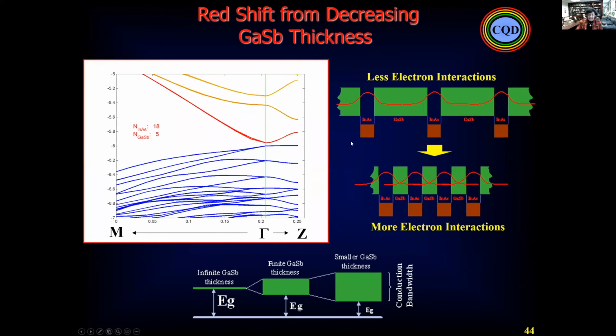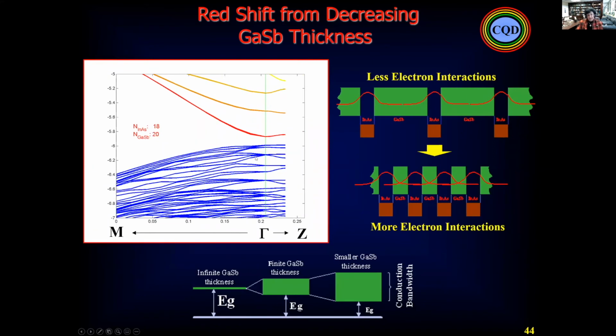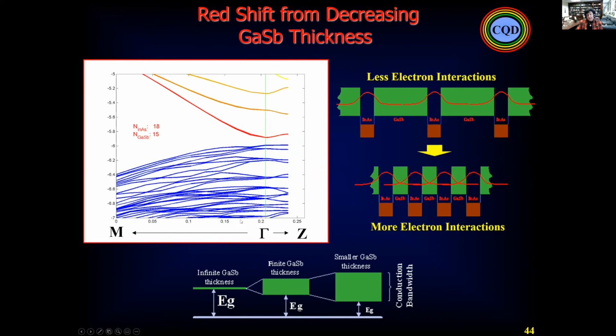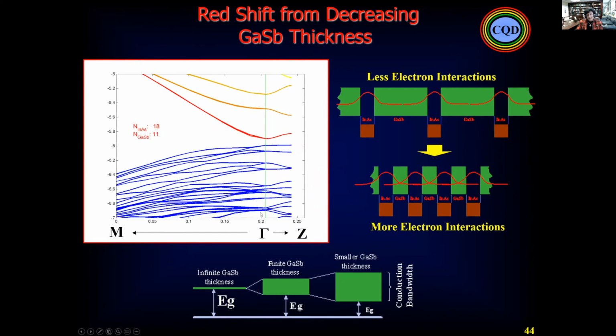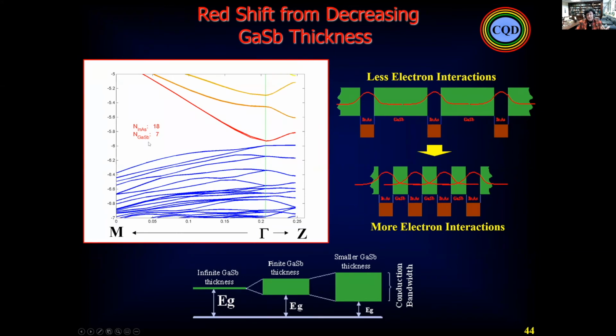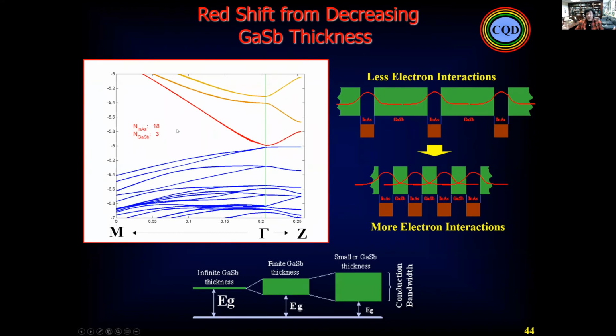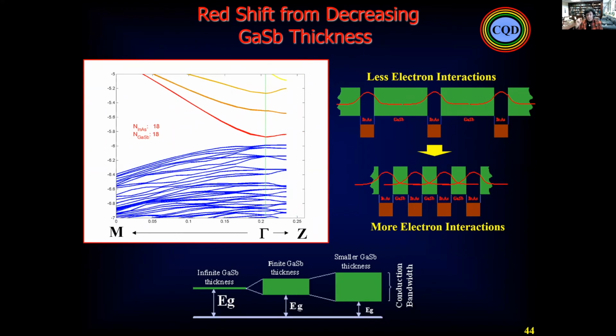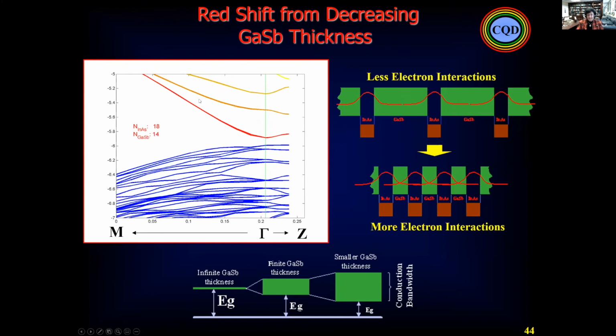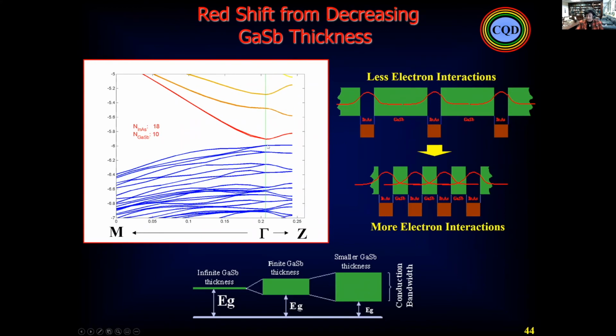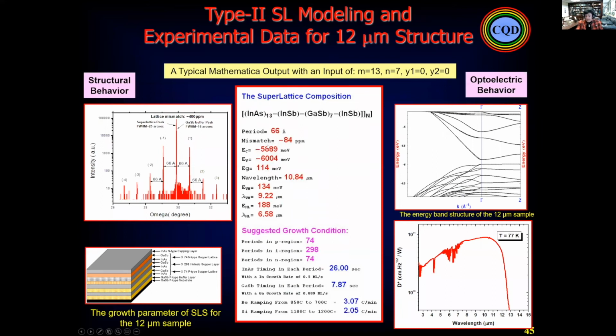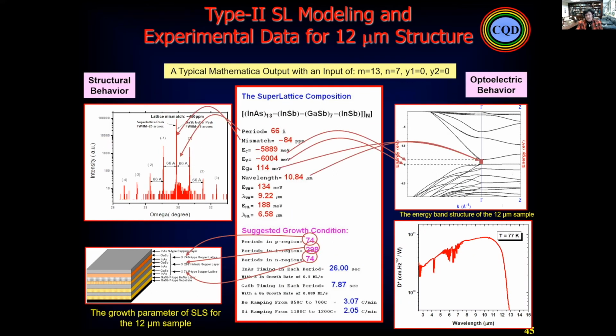And if you can see here, the ETBM theory shows that gamma is the center of the Brillouin zone. By using indium arsenide and gallium antimonide wide band gap material, by doing atomic and gap engineering, one monolayer chain, as you can see, you can change the gap. By ETBM you can have the different parameters to optimize and to have any wavelength that you want with excellent performance.